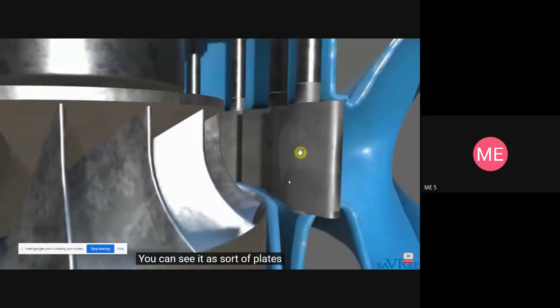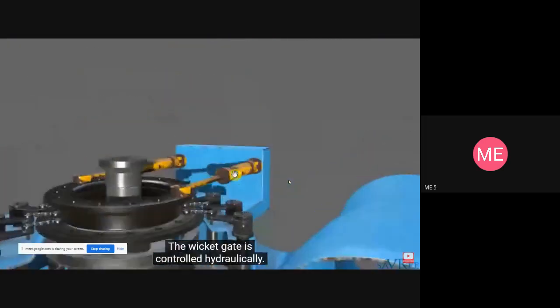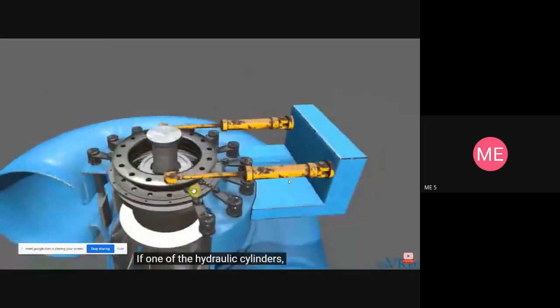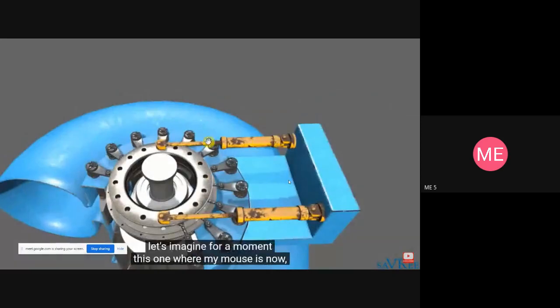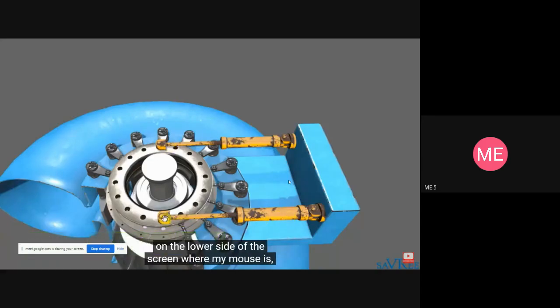See that they're sort of plates that are mounted between the water suction side and the runner itself. The wicket gate is controlled hydraulically. See, we've got 2 hydraulic cylinders here. Imagine for a moment this one where my mouse is now, if that was fully extended, then usually the other one on the lower side of the screen where my mouse is will retract.